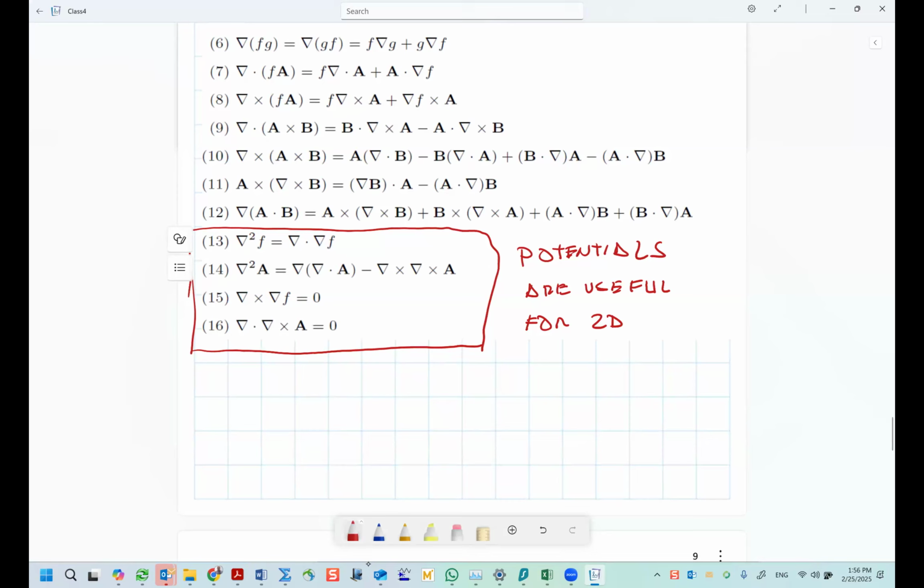But if things happen like in machines, let's say the windings of a transformer, the current goes in the direction of the winding, which follows the phi direction. So it goes through the angle. And if a conductor has only one dimension, potentials will allow, as we will see later, maybe not today, to reduce the dimension of the problem.